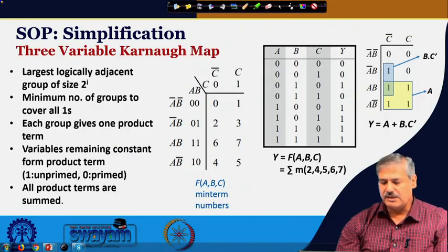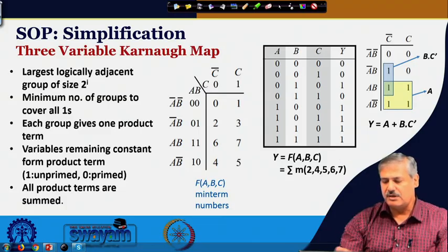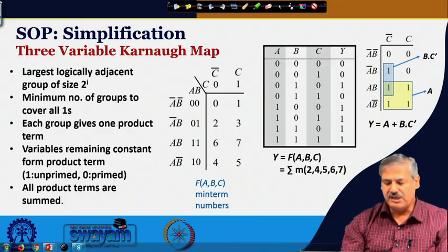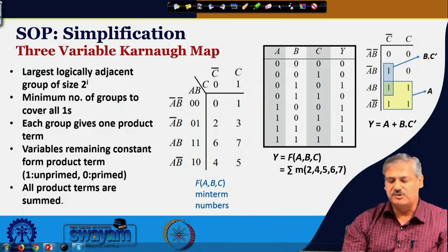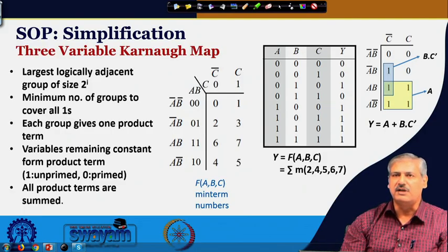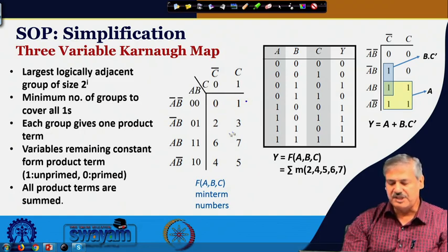Now, let us look at one example, a function where the min terms are 2, 4, 5, 6, 7. Here, for the corresponding min terms, we are not writing m0, m1 in this manner, we are just writing the decimal equivalent. So, 0 0 0 is 0, 0 0 1 is 1, then 2, 3, because a b bar, 1 0, is coming over here.